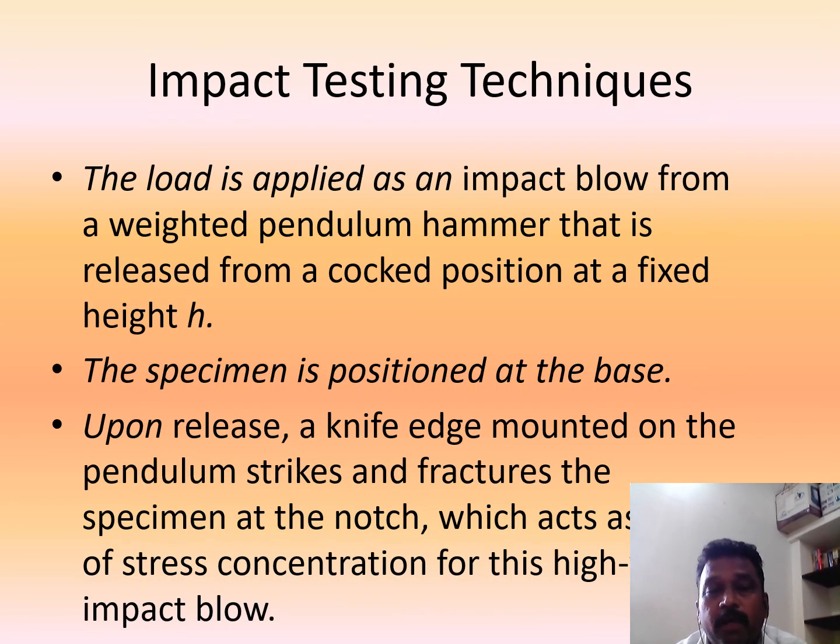The load is applied as an impact blow from the pendulum, and then the specimen, as I told, is positioned at the base. So this knife edge pendulum strikes and fractures the specimen. The notch will act as a stress concentration, so immediately the specimen will fracture.